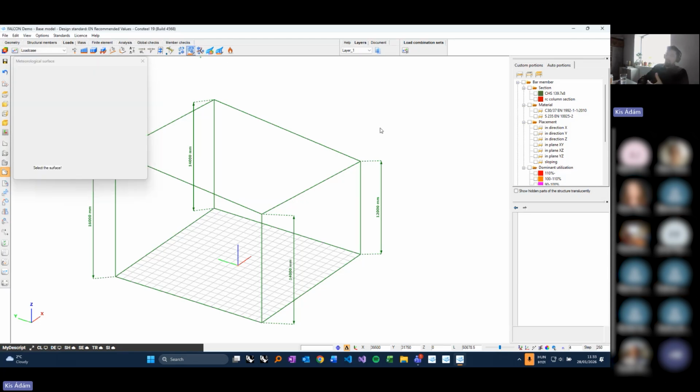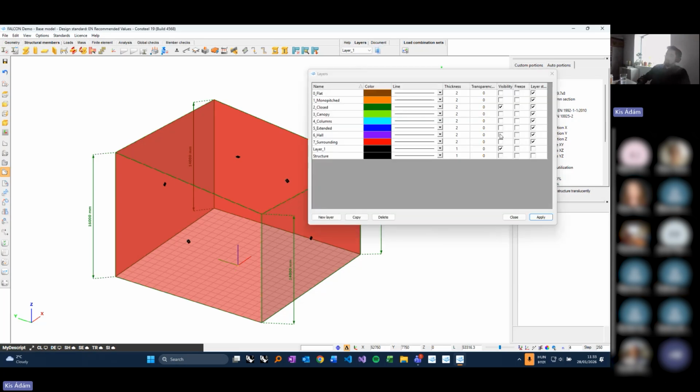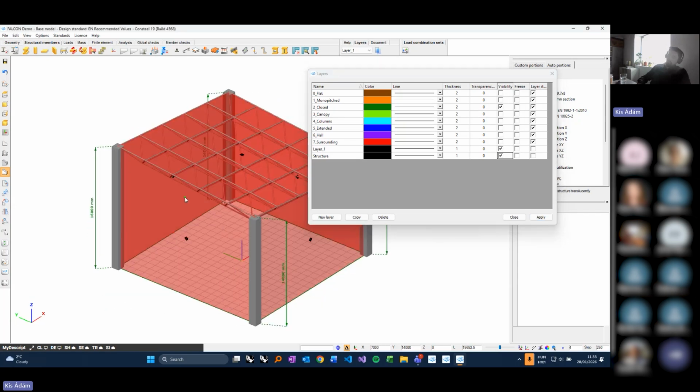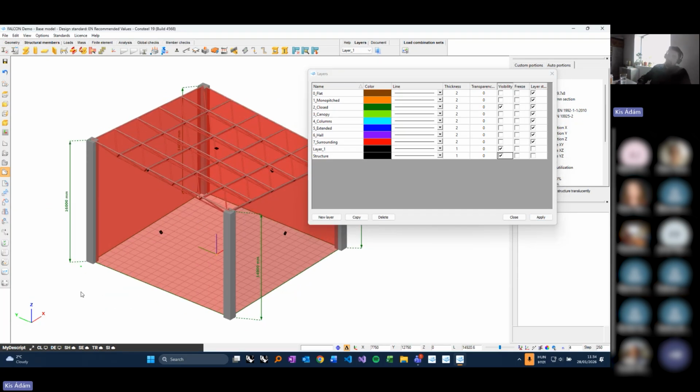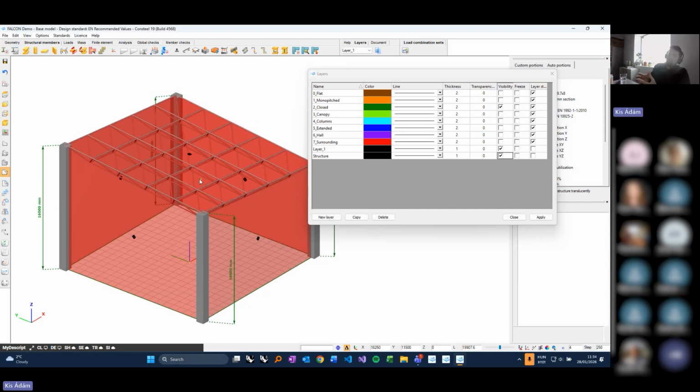So this was the most basic information that we have to define regarding the meteorological effect. Then we have to place the simulation surface, which is just a simple selection of the surfaces. But it is really important that if I would like to consider something in my model, I have to assign this meteorology or simulation surface. Even if I have a structure in my model, the columns and other steel elements won't be considered in the simulation, because everything for FALCON has to be modeled as load transfer surfaces.